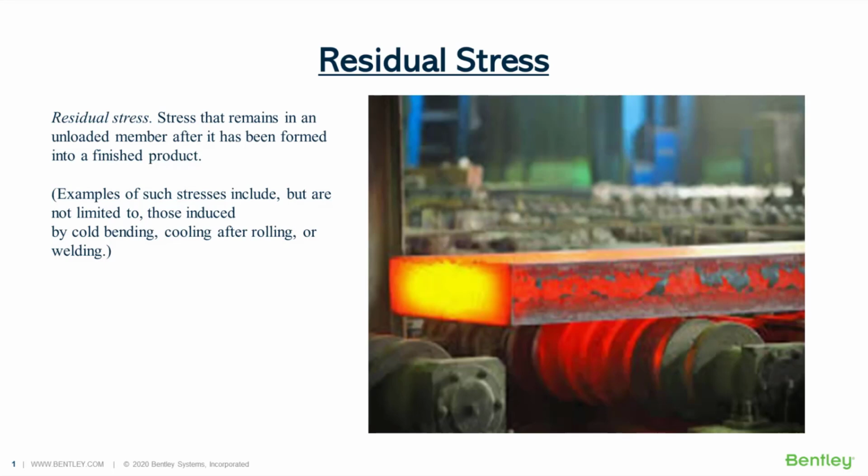The hot rolled steel section goes through several stress variations as a function of temperature change. See this picture, the rectangular section is being hot rolled from its manufacturing unit. Now at this stage the center portion is glowing more than its surroundings, and this is because the outer portion, owing to the vicinity of the cooler air, cools faster and then contracts.